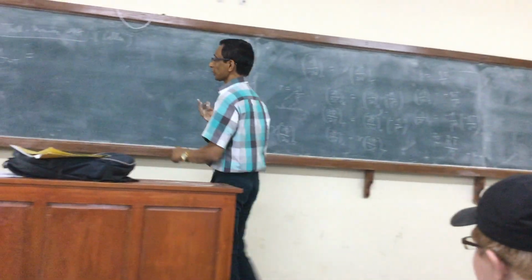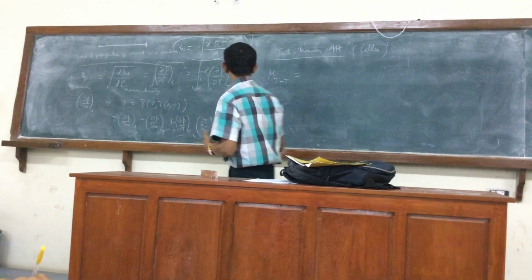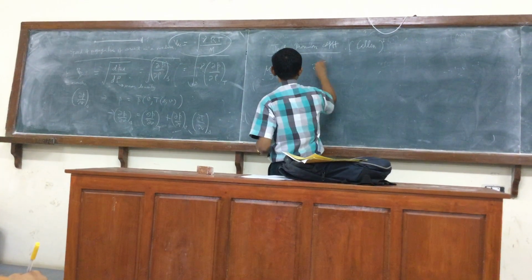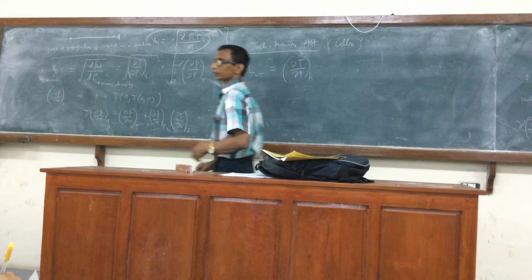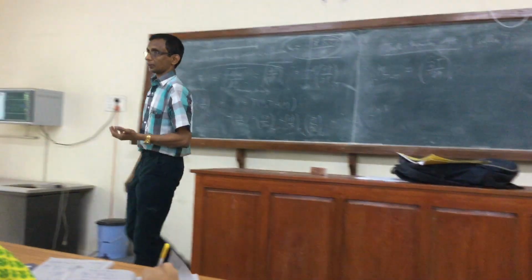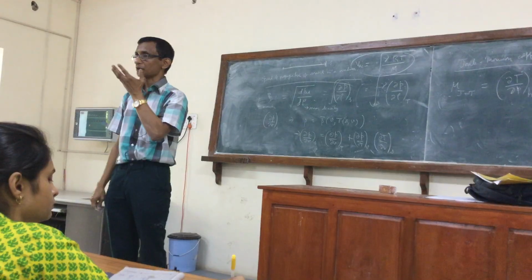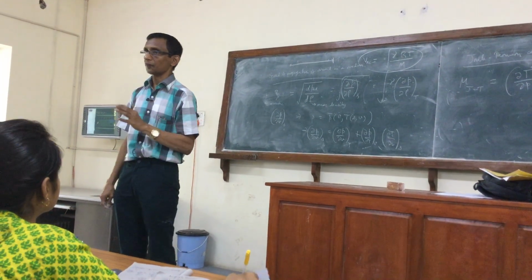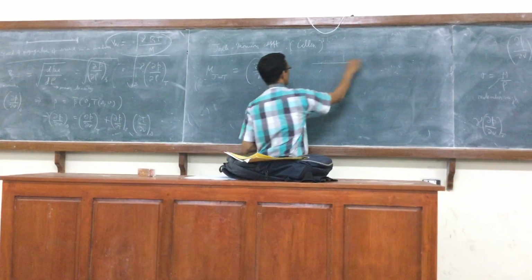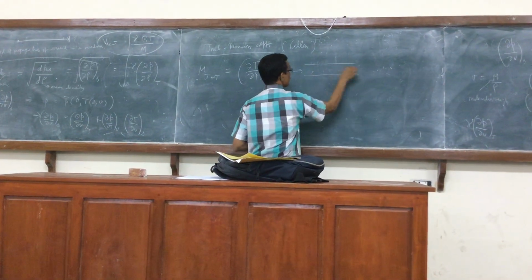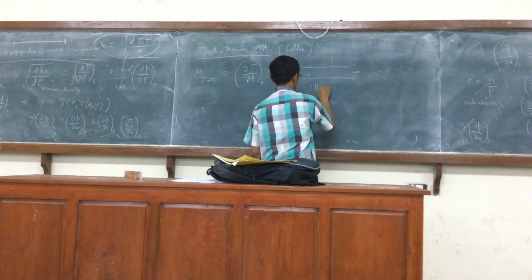The symbol is typically given for the Joule-Thomson coefficient. It is defined as the derivative of temperature with respect to pressure at constant enthalpy. Where is this significant? It is significant in the Joule-Thomson process, when you have a fluid undergoing what is called a throttling process.